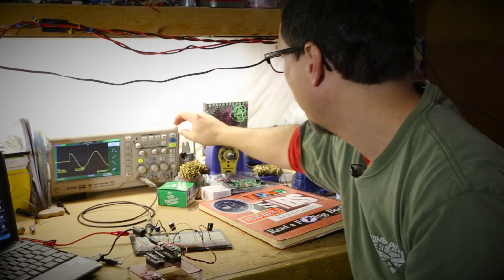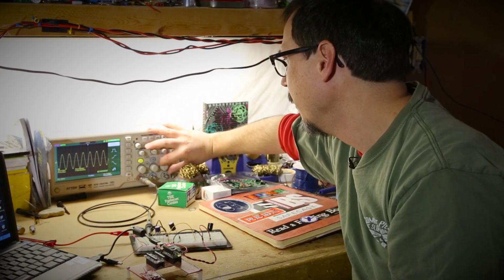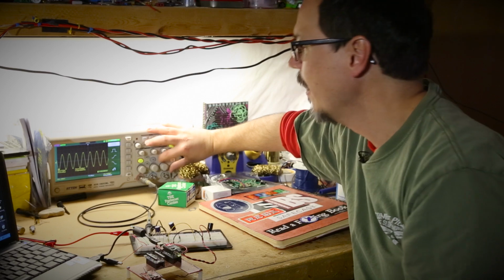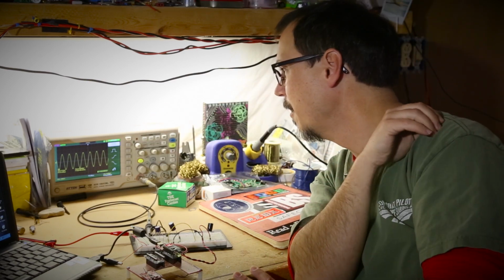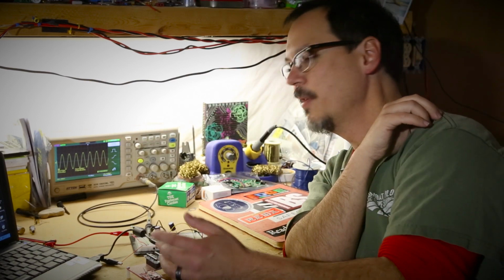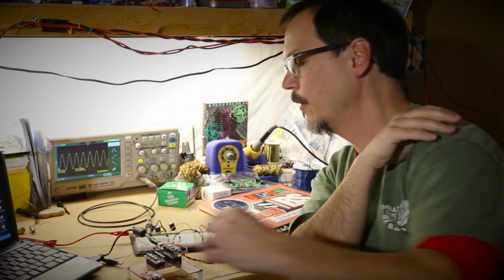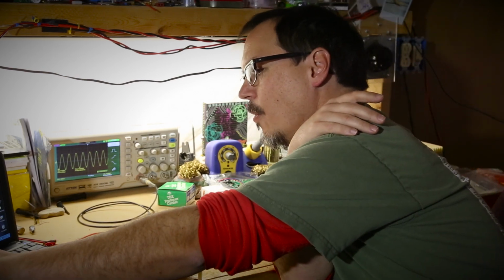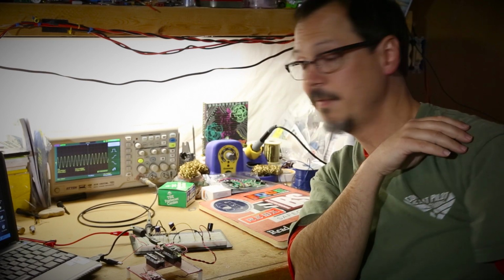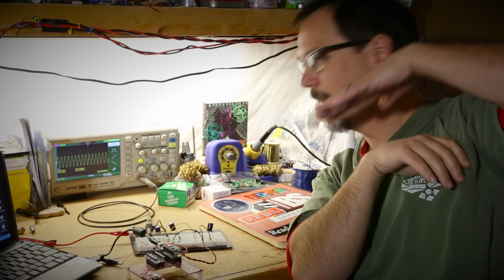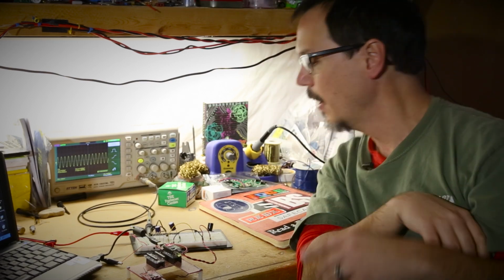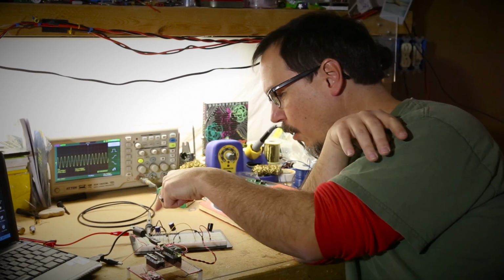Let's take it straight up to 500 kilohertz. So at 500 kilohertz, I'm at 800 millivolts, 784 millivolts peak to peak. So even at 500 kilohertz, I haven't reached the high frequency cutoff of that thing. Heck, let's go for 1 megahertz. Now I'm down to 552 millivolts peak to peak. So I'm still not quite at the high frequency cutoff. This is a pretty decent little circuit for being a whole bunch of junk